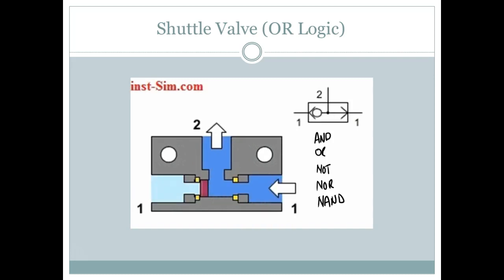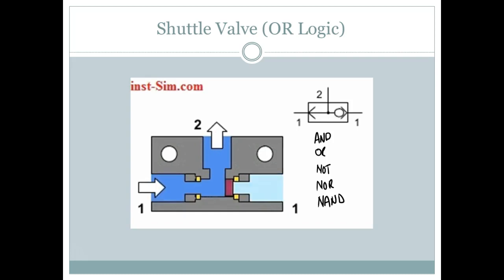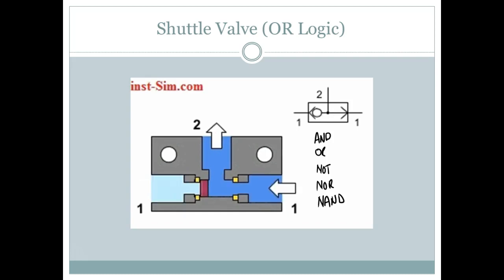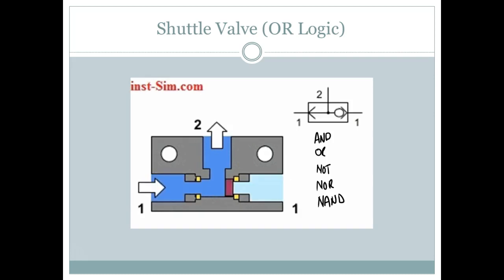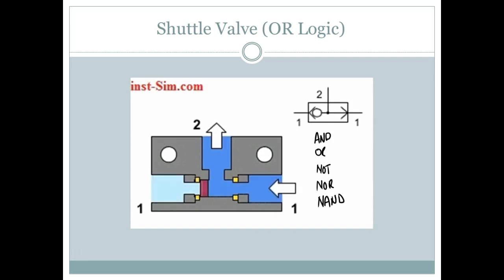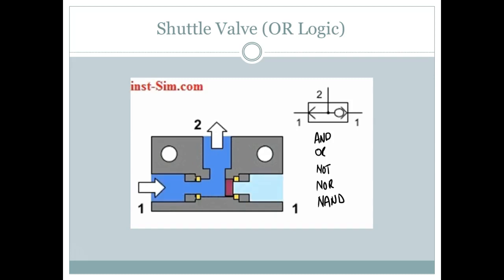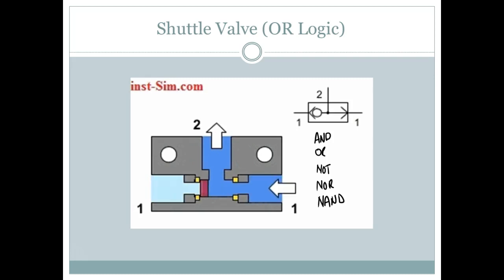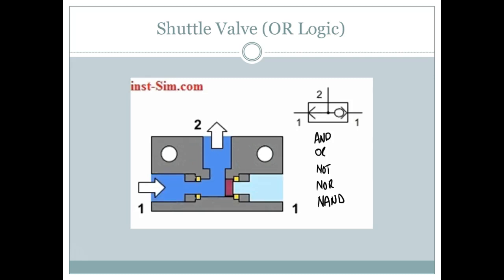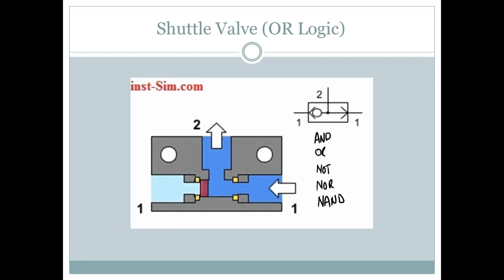That makes sense. So you see these used a lot, and that's one of the big things they do, where we can control something from 2 different stations, but one station, the one that hits it first, controls it, and the second one can't do anything to the first one. So it says 1 or 1 gives me a 1. That would be digital.